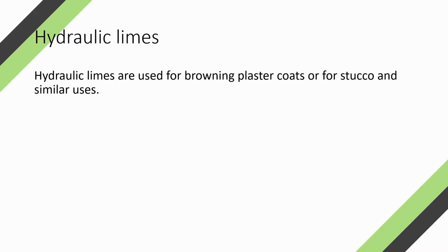So, it is made by burning siliceous or argillaceous limestone whose clinker after calcination contains a sufficient amount of lime silicate to give hydraulic properties to the product. So, hydraulic limes do exhibit hydraulic properties but are not suited for subaqueous construction because they require free access of air during hardening.